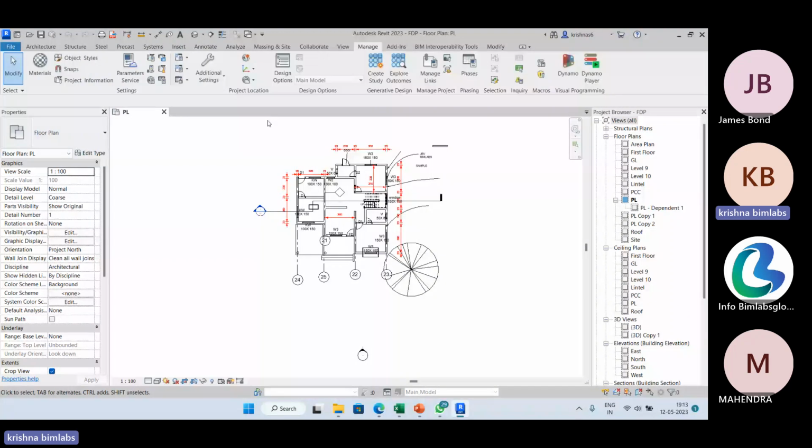If you're working in a BIM model, you have to follow some standards. When you open a project in Revit, the first page you see should be the project information. When you get a 2D sheet, there is already a title block where all the related information is. Likewise, when we are working in a BIM project and you or your client opens the Revit software, the first view should be set as a project information view.